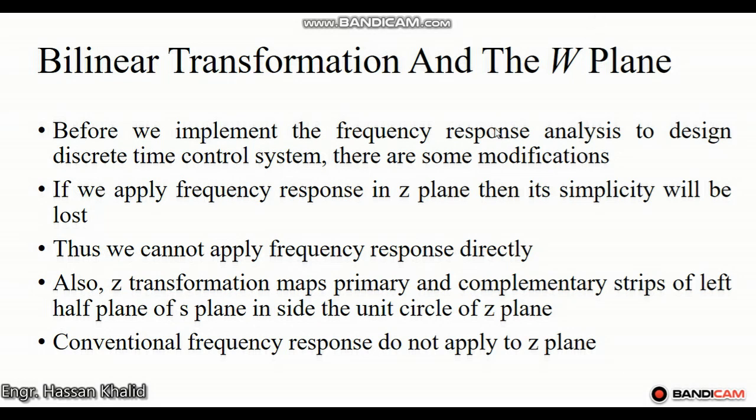Now, the next topic is the bilinear transformation and the w plane. Before we implement the frequency response analysis to design our discrete time control system, there are some modifications. If we apply the frequency response in the Z plane, we will not be able to apply it directly because the simplicity of the Z plane will be lost.